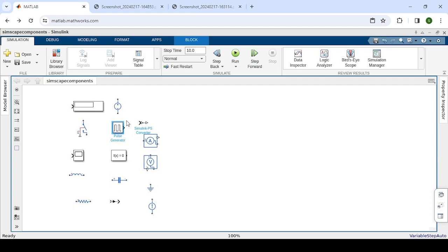If a pulse is at its highest value, its peak value, maybe a maximum amplitude of 1, that will simulate the circuit being closed, and when it is on 0, that will simulate the circuit being opened. That's how we can use this pulse generator to control a switch, and we can just vary the parameters of the pulses. We can change the duration of each pulse, we can delay each pulse, and do a lot of other things with the pulse.